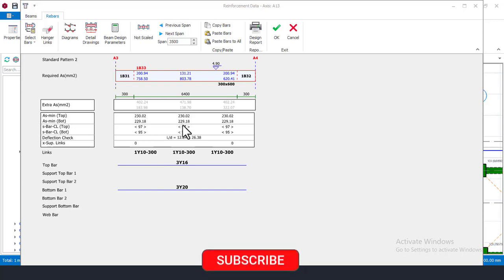As you can see, for the top reinforcement we have 3Y16, and we have 3Y20 at the bottom, and for the links we have Y10 at 300 spacing. That's fine. So when you're doing your beam interactive design, it's good to try to use smaller bars first. Except they're not sufficient, you're not going to use a bigger bar.